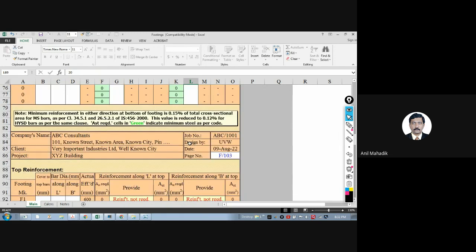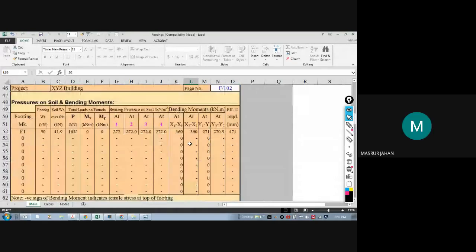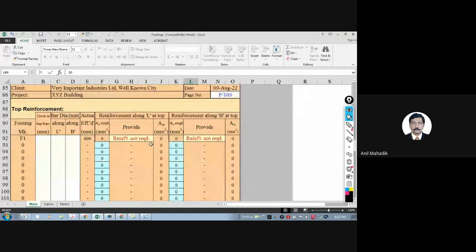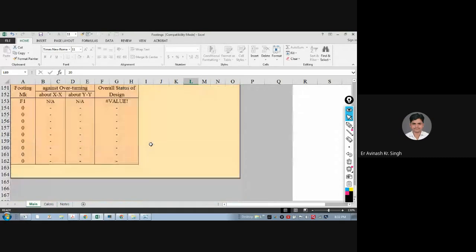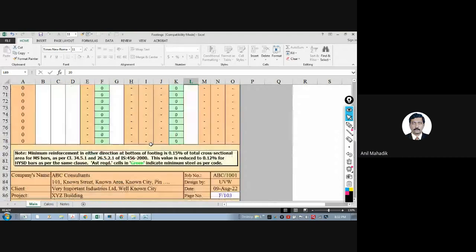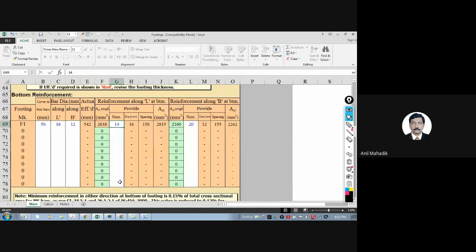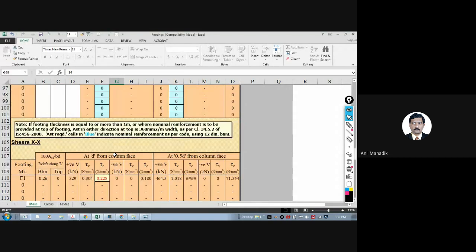Now you got this procedure. Yes, sir. Now it is still red. Where is the red? Here. No, in the 13 one. Is it red? Yes, 14 will come, sir. 14 at 150 spacing. Okay. So here top reinforcement is not required. Only bottom reinforcement is what we require.